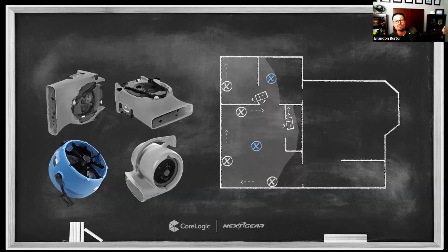You just went from a class 2, right, which is relatively easy to deal with. And if you don't follow classes yet, another homework assignment for you, but that's basically describing where the water is and how much is present. You're going to go from a class 2 to a class 4, right, which is difficult. It's challenging, right? It's specialty drying. So I have to address all of these surfaces initially. If I don't, those areas are going to get worse in the first 24 hours. Those are the problem areas you end up dealing with on day 4, day 5, day 6. Those are those problem areas, the ones that didn't get addressed with air movement on day 1, right?